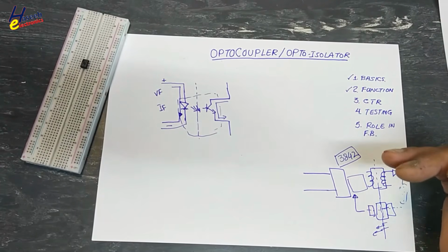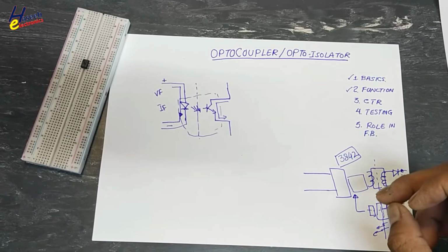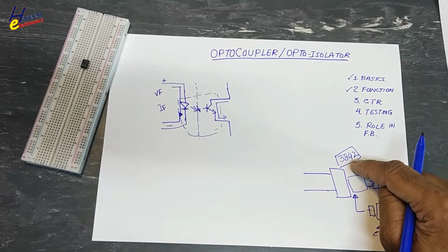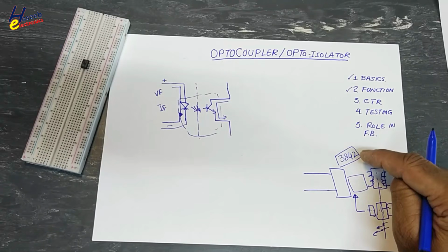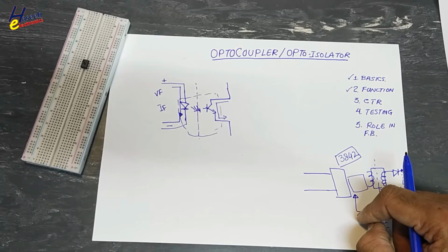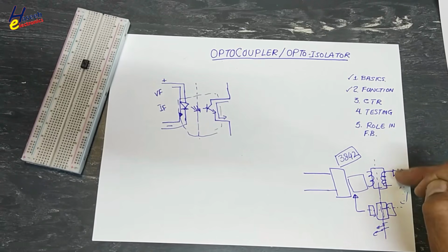If switching frequency is low and we are demanding function very fast, this IC will not respond. If it is switching very fast and we are designing any feedback loop with slow response, there will be ripples. For a best design, error amplifier current must be considered carefully.